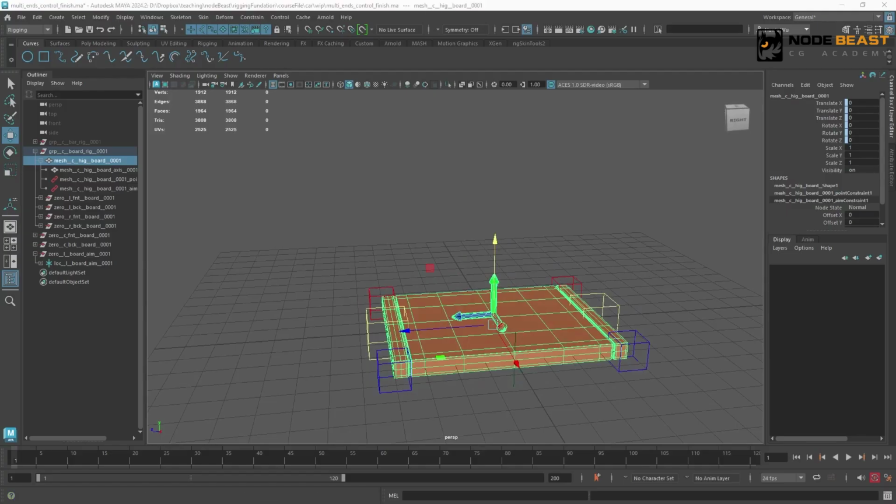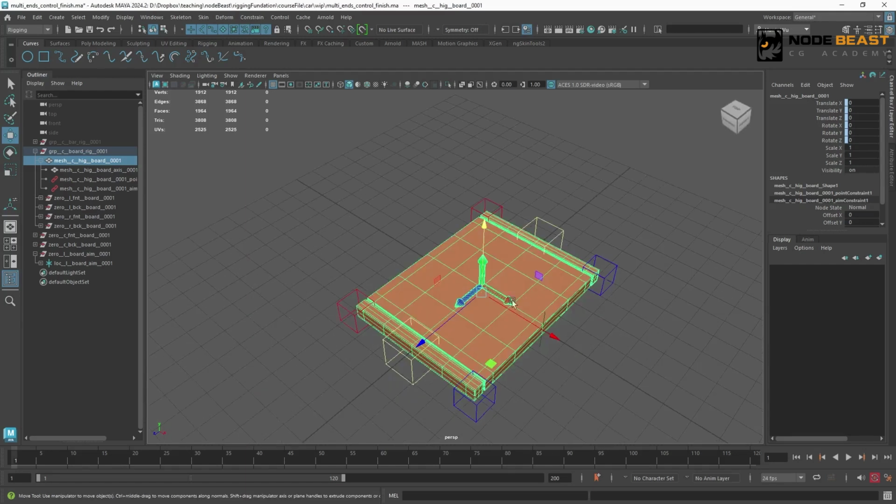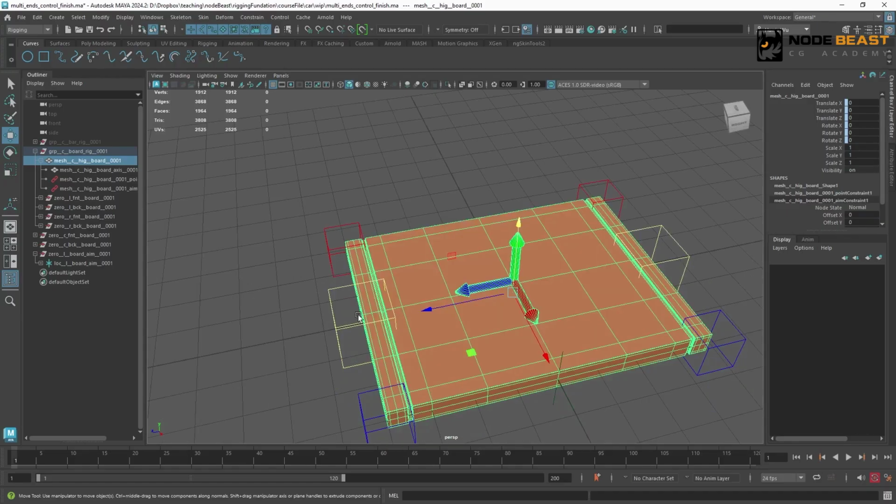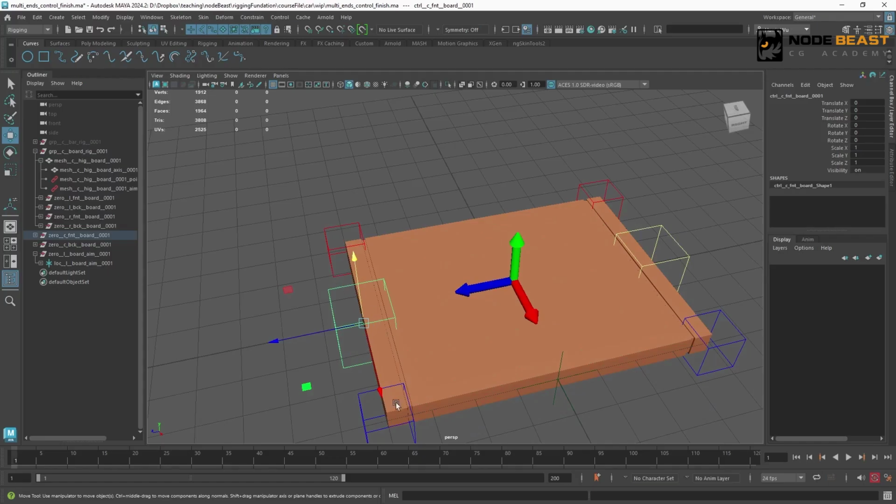If we recall the aim constraint, we should remember the aim constraint requires us to define the orientation of 2 axes to get a final rotation value. We've been using the world y-axis as the up vector. This is clearly not allowed for rigging. We've already used the x-axis as the aim vector to define its orientation. So next we can take that up vector, which was using the y-axis, and we can change it. What do we change it to? We can change it to object up, using the center position of the two front controllers as the reference object to make the z-axis always point at it.